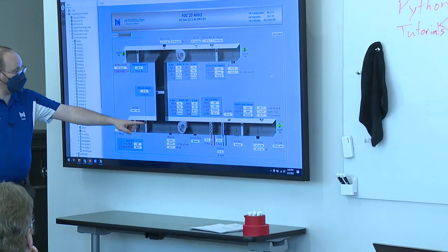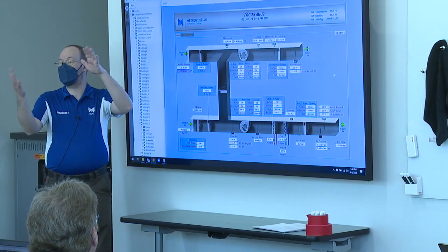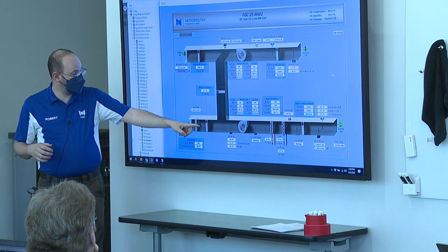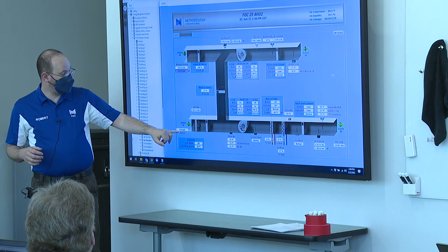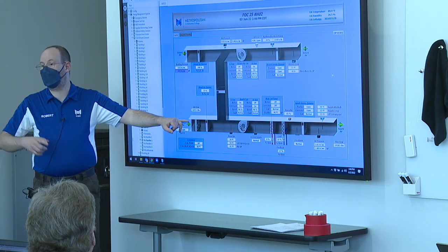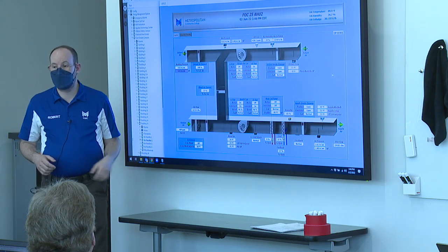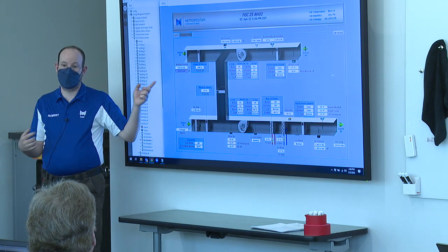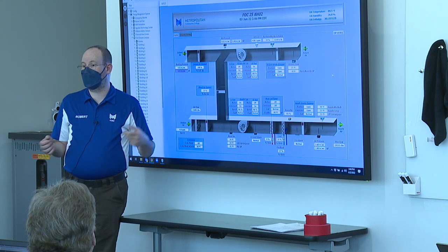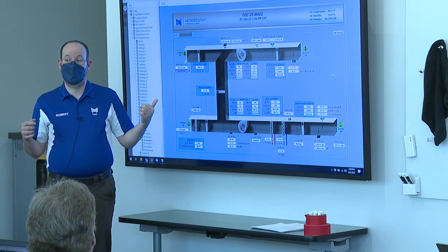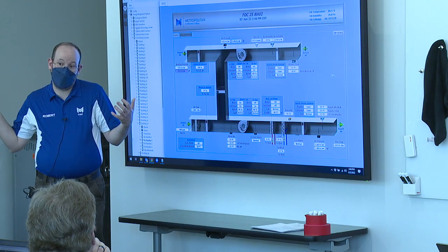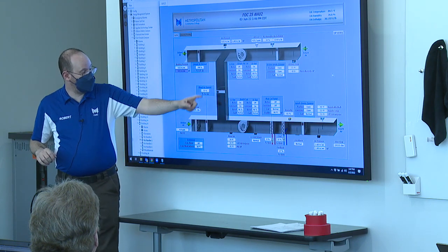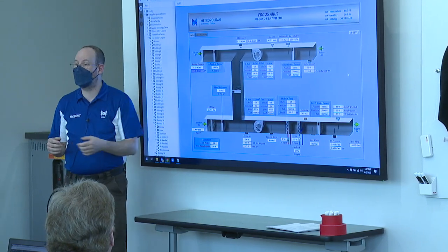We may have dampers that are showing a relative position versus what they should be. So we're at minimum outside air right now, reading 450 parts per million CO2, with about 16,000 CFM of outside air. One of those things where maybe somebody should be looking at this saying, do we need 16,000 CFM of outside air for a building that besides us has like 6 people in it right now? Anyway, we can see that our dampers look like they're just partially open.